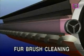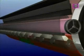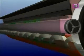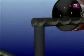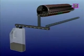To enhance subsequent cleaning efficiency, lowering the electrical potential of the drum surface allows paper dust and residual toner to be cleared from the drum by the grounded conductive fur brush. The toner adhering to the fur brush is scraped off by the flicker. In the cleaning process, the toner remaining on the drum is scraped off by the main blade and collected by the recovery blade. The collected toner is then stored in the toner box.